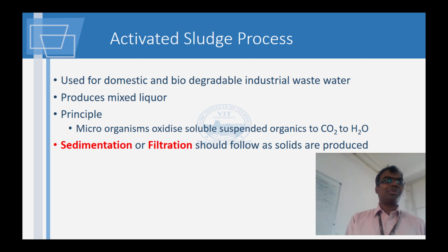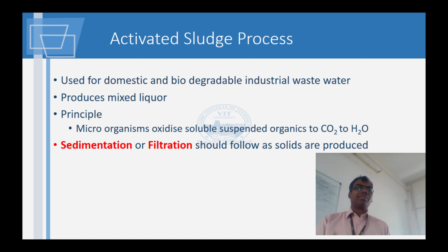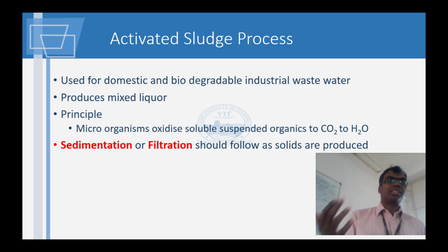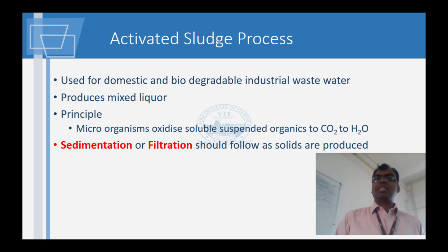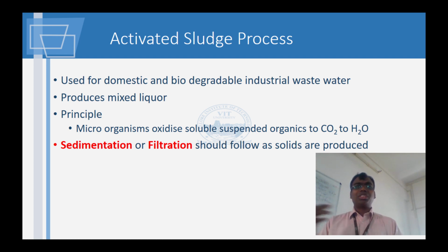For the activated sludge process, we need something with a lot of bio content, a lot of BOD content, especially BOD 5. There's BOD 5, BOD 21. You can also go for much longer periods of determining BOD, but BOD 5 is where you have mostly all the biological substance. Whatever you get out of this system, the effluent of the activated sludge process, is called mixed liquor. It is a high quality effluent which has a lot of stable suspended materials, in a more or less homogeneous distribution.